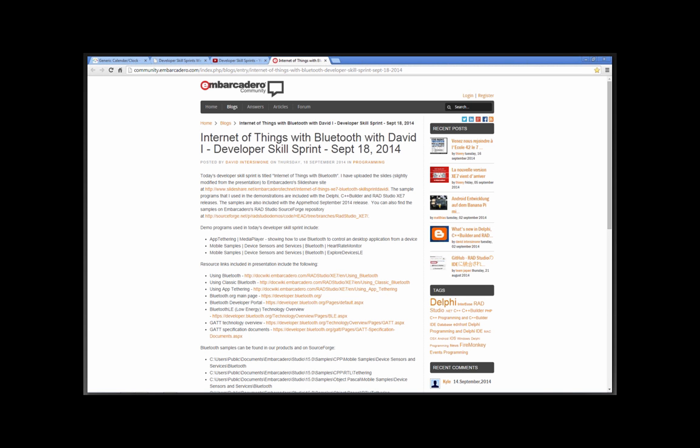If you look at the source code in the heart rate monitor sample, you'll see the first part of the UUID being that number. The rest of the bytes of the GUID or UUID are basically the same. They're all the same bit patterns. They can be used for other things depending on the device. But ultimately, when you look for a specific category of device, or if you just say discover all the devices, that's that method that I showed.